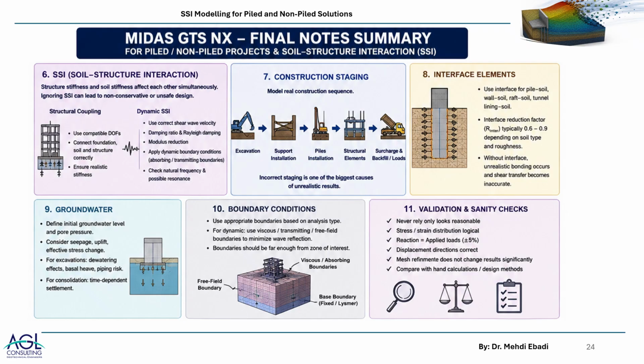Groundwater and seepage. You have the option to use coupled analysis of seepage, dynamic, consolidation, everything in MIDAS. But again, you should make sure that the elements that you're bringing in to be considered are the elements that would influence the design within the engineering accuracy.